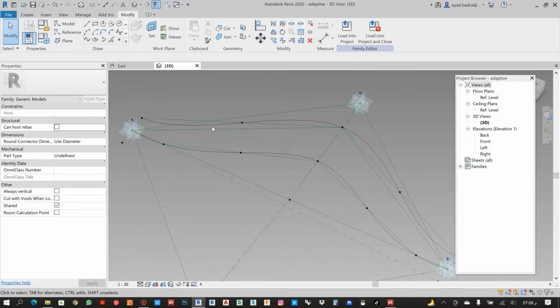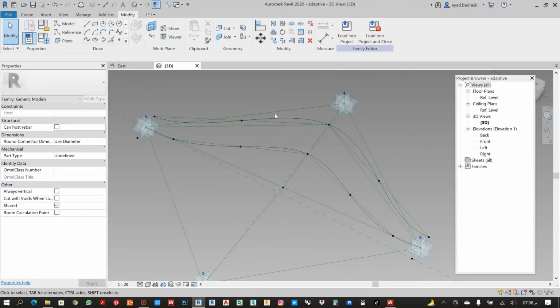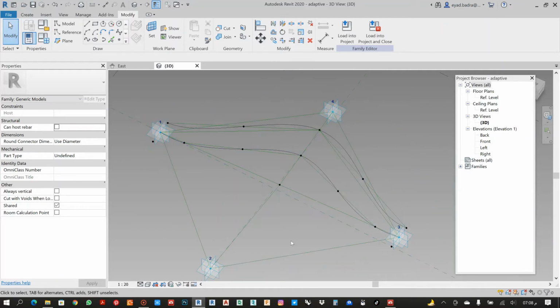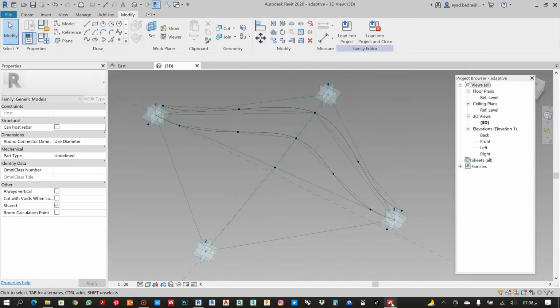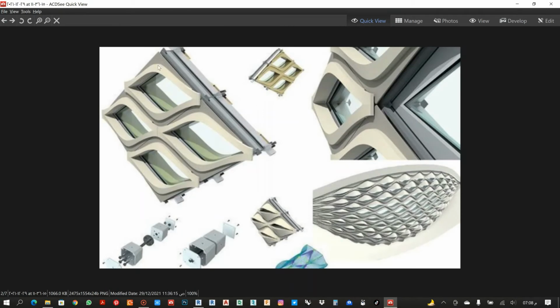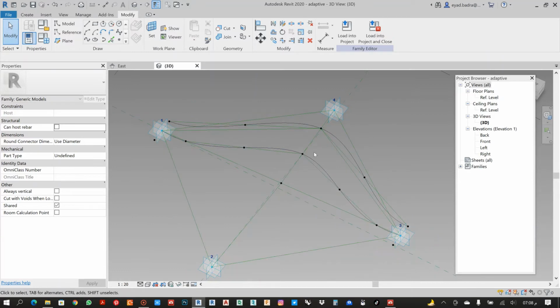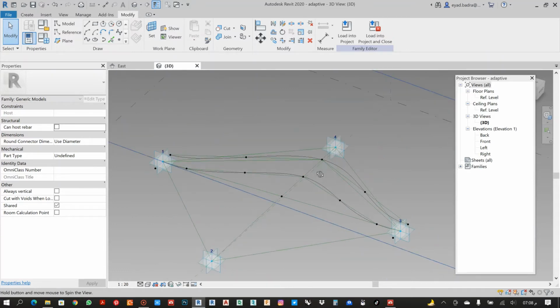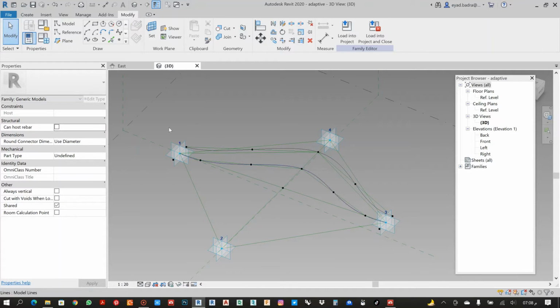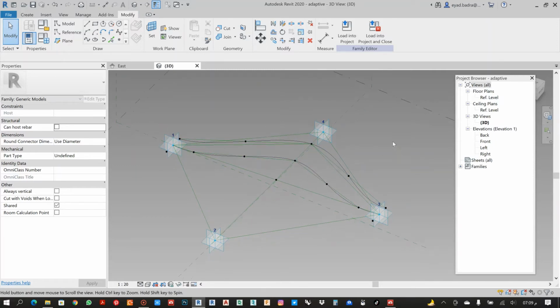And then it will be very easy if I connect these 2 lines and these 2 lines and make a normal extrude or create a form. But the problem is the shape is not like that. It starts from 0 until thickness. So I don't have a thickness here, and then this side also has a thickness. So that's why it makes the shape a little bit hard to do. So we will start now to make some offset points and also some external lines and some external SP lines to connect it and make the shape separately by faces.